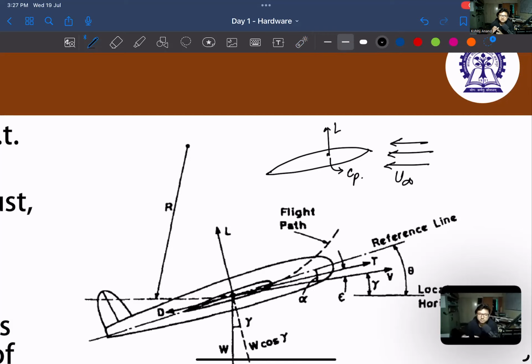And because it is at that point, around that line of points, the lift is maximum, and more or less the average lift vector will be pointing out from that place. What we try to do while making an RC aircraft is we try to keep the CG ahead of this. And why is that the case? Because you have a tail in the aircraft and you have the main wing in the aircraft.